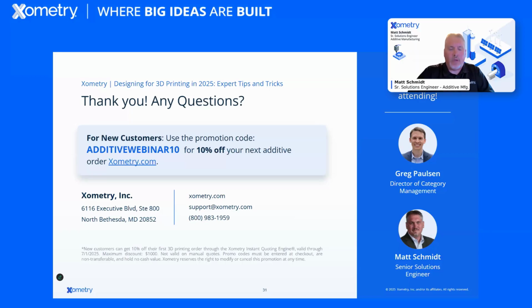Well, that would depend on a couple of specifications or requirements. One being tolerances. Of course, when you print in different pieces, you're going to have a different stack up rate. If parts are plus minus 15 thousandths for each part, you're going to have much more stack up than building a larger part. With processes like FDM, you can take advantage of custom infill percentages.